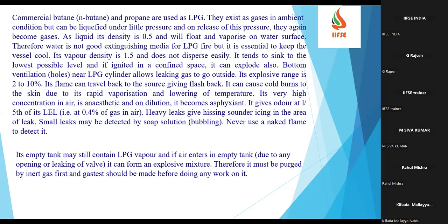And if ignited in a confined space, it can explode also. The bottom ventilation holes near the LPG cylinders allow leaking gas to go outside, and its explosive range is 2 to 10%, and its flame can travel back to the source, giving a flashback also. That's why we use flashback arresters in industrial operations. Here we use regulators, which also have a flashback arrestor system.